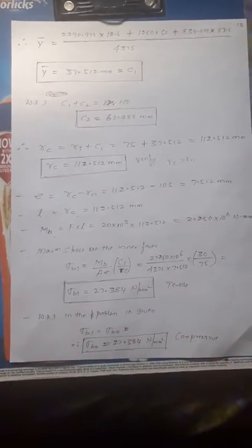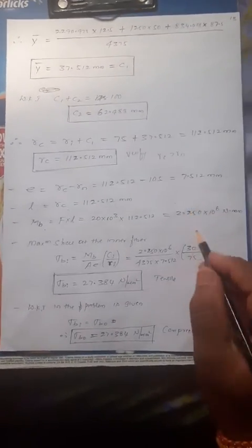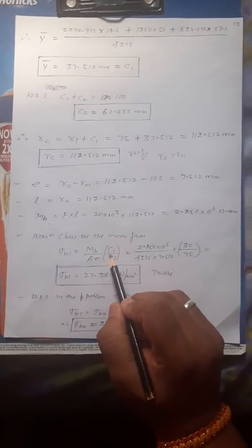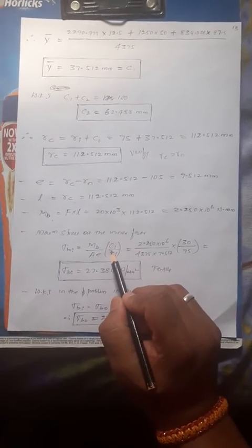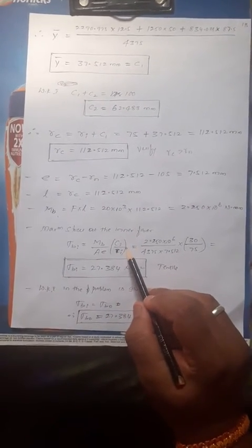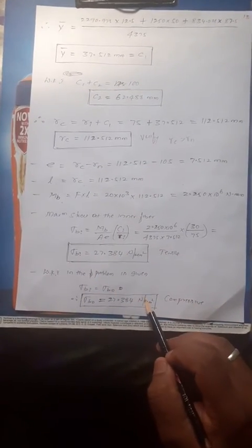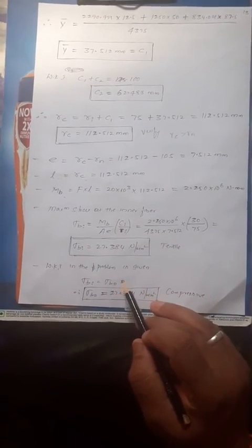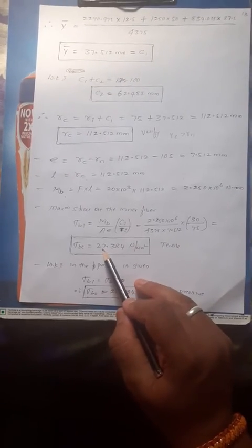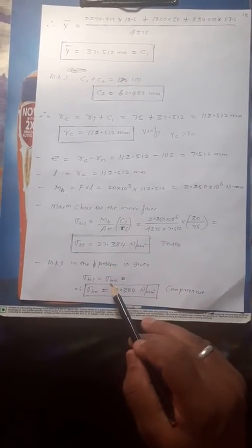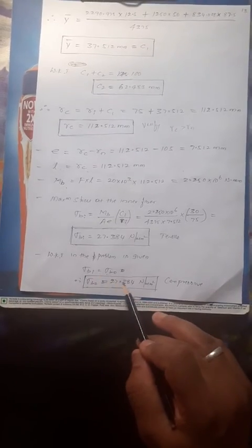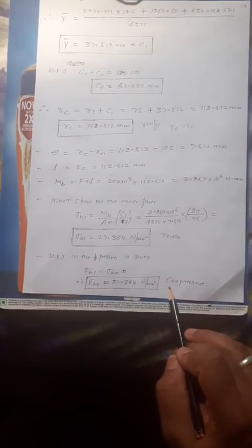Then what is the maximum stress at the inner fiber? We already know from equation 25.55, I think. Then you'll get that the inner fiber undergoes tensile stress, and from 25.54, or you can know from the conditions given, the bending stress at the inner fiber is equal to the bending stress at the outer fiber. Then you'll get this one, but compressive in nature.